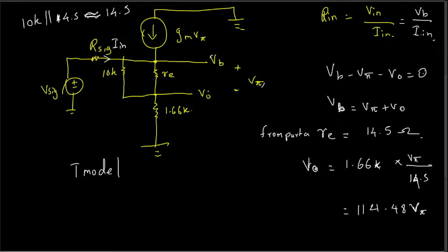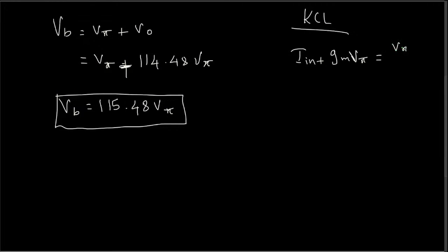If we express this in terms of Ohm's law, V is equal to I times R, therefore I is equal to V divided by R, and the voltage right here is V5, and the resistance right here is RE. So this should be equal to V5 over RE.